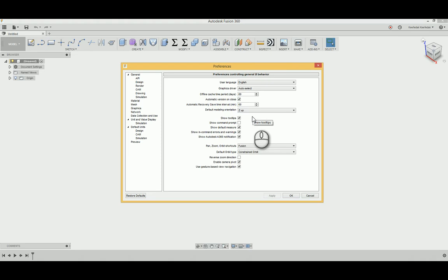The reason we want Z up is that whatever you model in here, you can send the code out to the 3D printers, to the multicam, to the Haas, to the laser, to the plasma cam, anything that is a CNC or computer numerically controlled. What you design here can go to that machine.